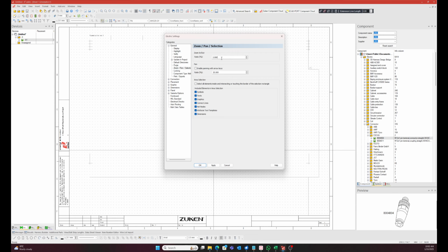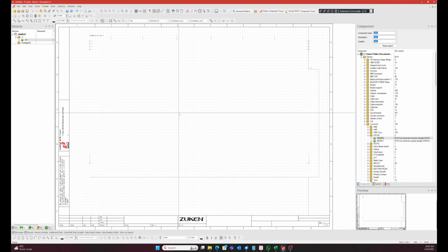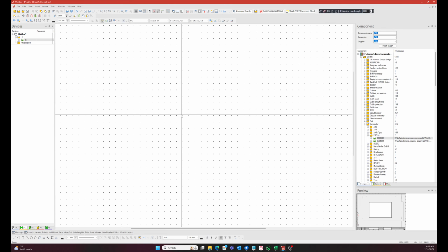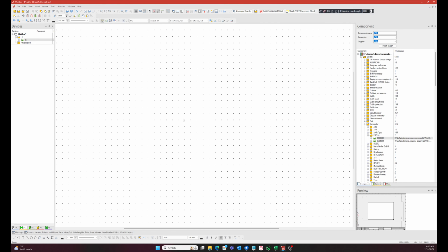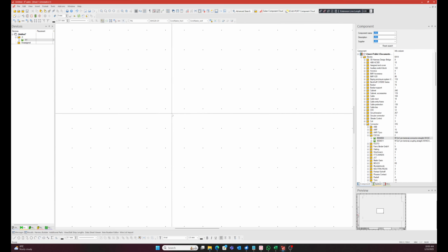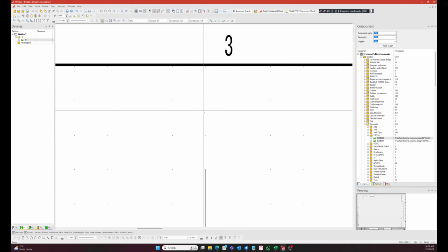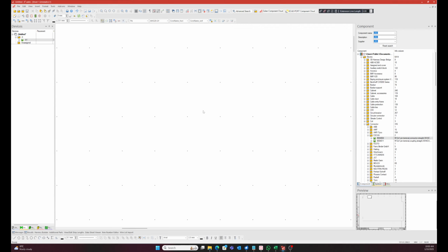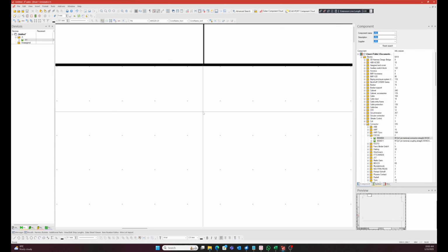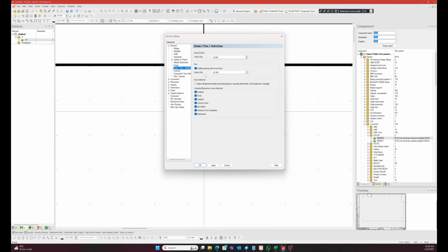And then zoom pan select. The zoom in ratio is really slow, so I change it to 15 and I also enable panning when arrowed. So it means that when I hold control and scroll, it's relatively quick without being too quick. By default, you need to do a lot of mouse scrolling to zoom in. And then once I've zoomed in, I can use my cursors to go left. If I go up the top, you can see that I can go left, up, down. Again, you can tweak it whichever way you want, but this is sort of where I found it to be helpful.